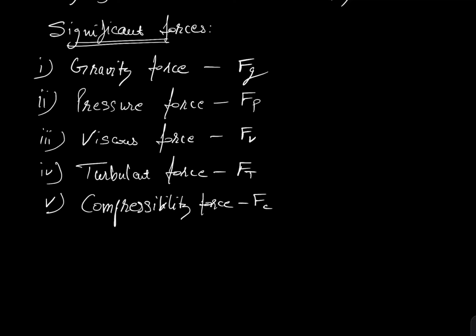Okay, so I can say what is the net force that is acting on a fluid. It will be F equal to Fg, force due to gravity, plus Fp, force due to pressure, plus Fv, viscous force, plus Ft, turbulent force, plus Fc, compressibility force, right? These are the total forces acting on a fluid at any instant, at any location.